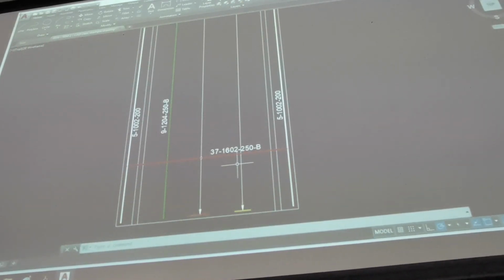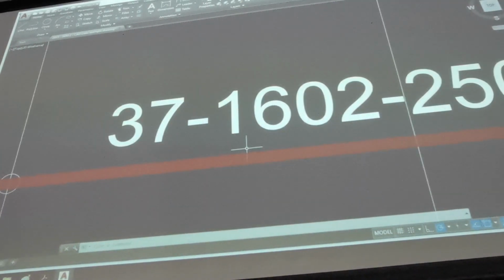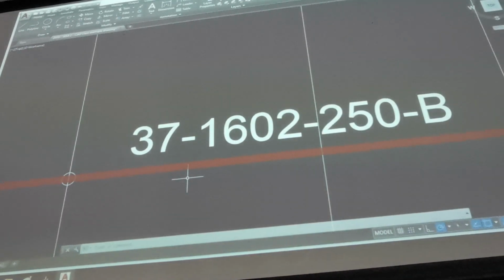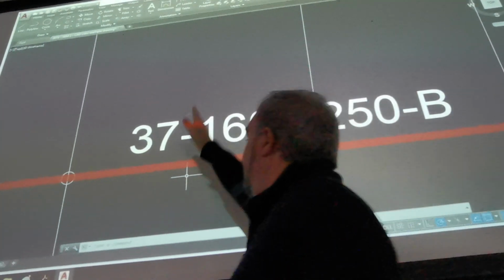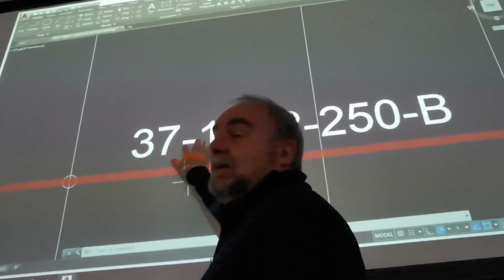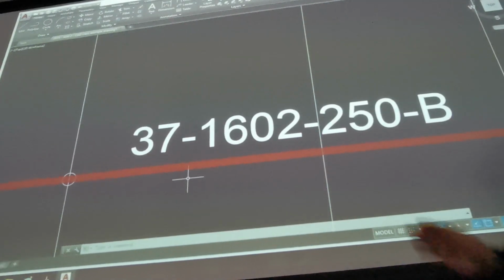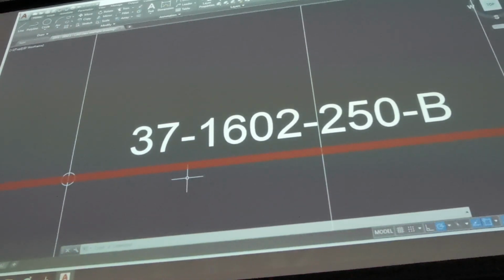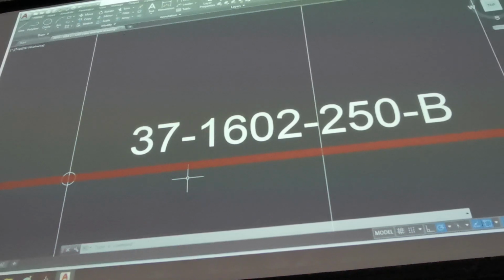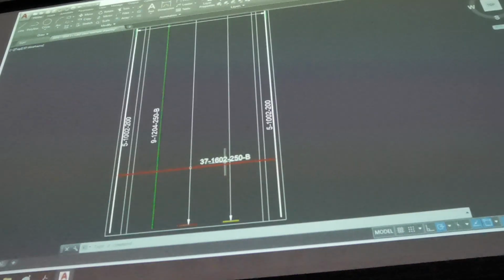The next thing is I was talking about Tetris. See these numbers here? Notice how my line comes down and comes between the two letters where this is. That's perfectly acceptable. It is not acceptable, and I'm going to say this for the second time now, to put lines through text. And that's what makes this drawing so damn hard to do, and it's what makes it really hard to do with an hour to go on Sunday. Okay? So don't put lines through text.